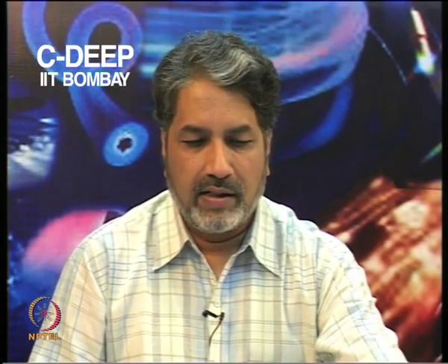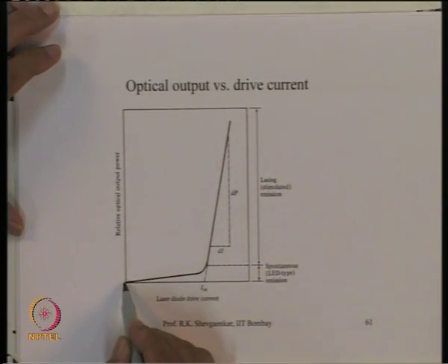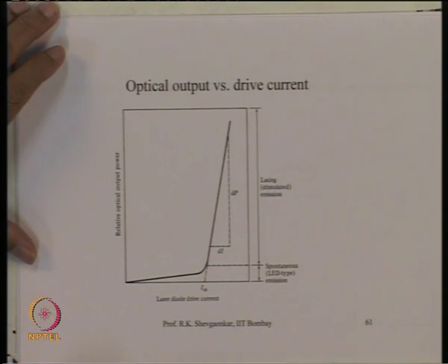Another important aspect of this now is that when we supply the digital data to the laser diodes, the photons will get excited inside this, but then if the laser initially has no current applied, if the current is brought to 0, then when we switch on the current, the population inversion has to build to a value which corresponds to this threshold current, and beyond that only you will see the stimulated emission.